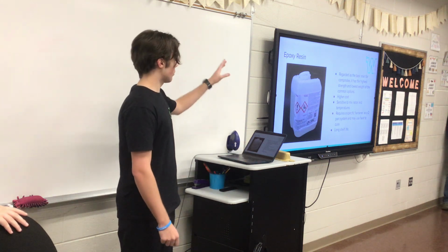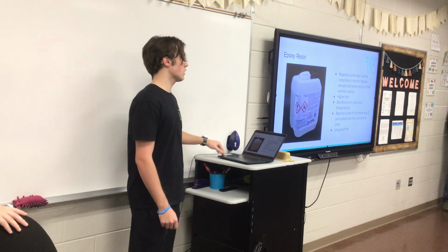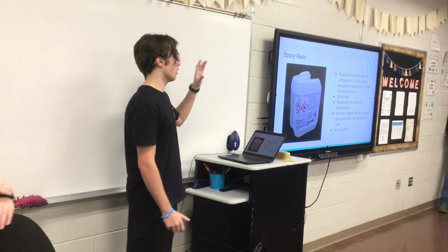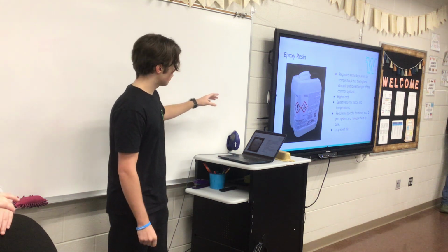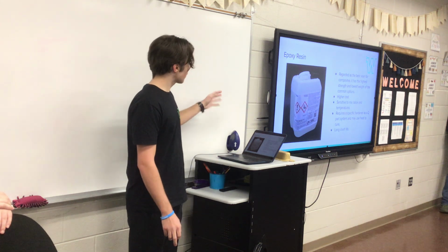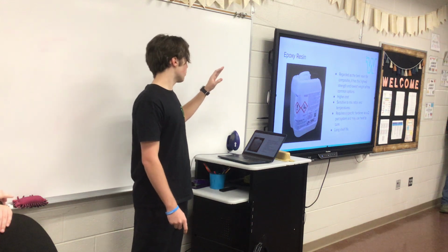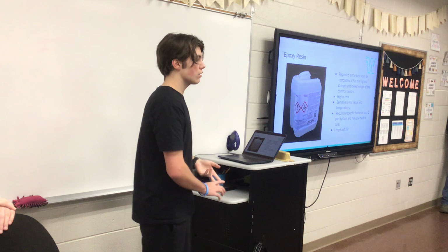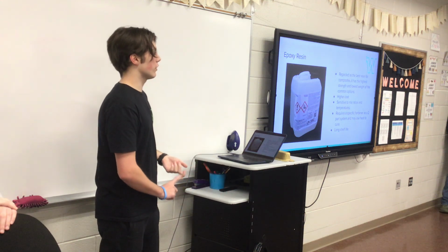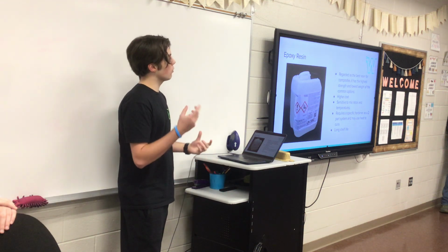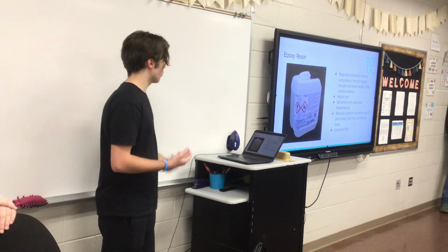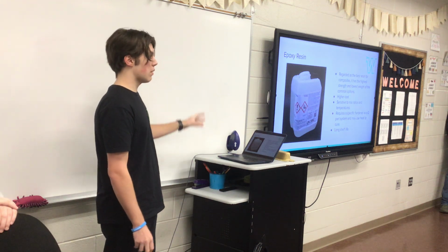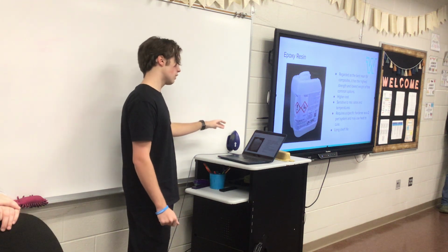So here's just some more stuff about epoxy resin. It's often seen as the best for composites because it has the best strength and lowest weight out of the common options. It's going to have a bit higher cost, and epoxy resin you need to be careful with. It's a two-part resin, so you're going to have your activator and you're going to have the resin itself. So you have to make sure you have the right ratio for however much you want to use. And it's exothermic, which is a safety hazard.